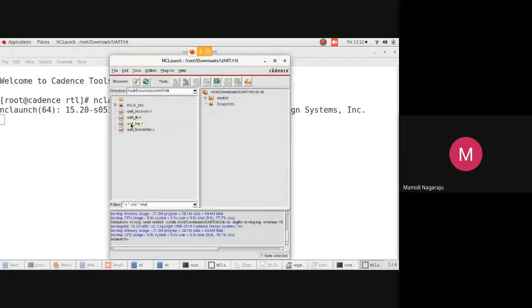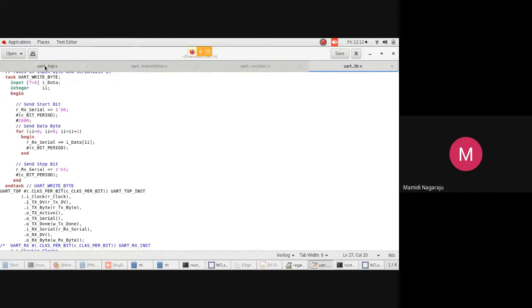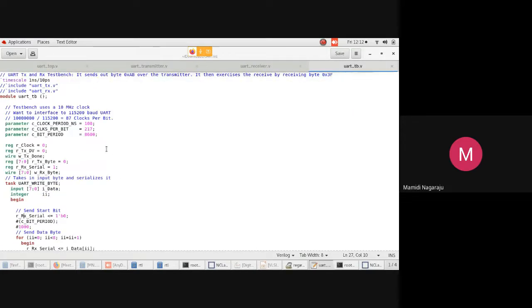For your reference, I would like to show you one small error, so I generate one error and we'll see if our tool shows the error at the particular line. Let's say I forgot to close the register here. This is the line number. I'll close it. The second one, a syntax error: I forgot to use the semicolon here, then the TB test bench code.